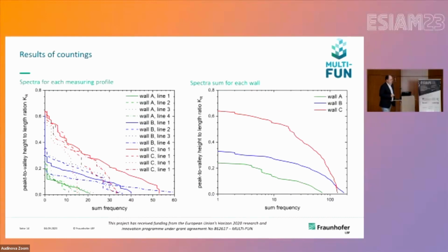Now it's important for the fatigue that you find the weakest link. That means we are not interested in this. We need to know the highest value. And therefore, just add these spectra, and you get this one. Here you can see, for the red one, due to the shape of the spectra, you are nearly sure that you have found the highest value.